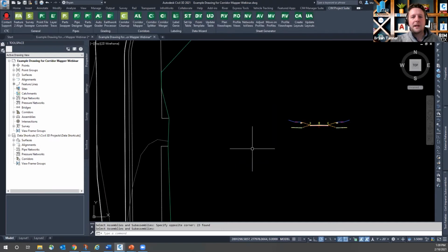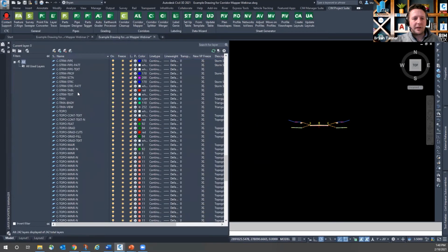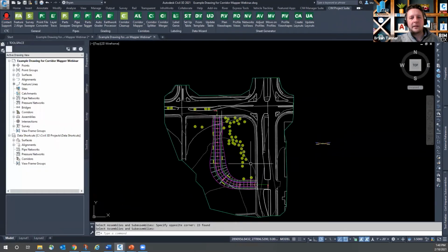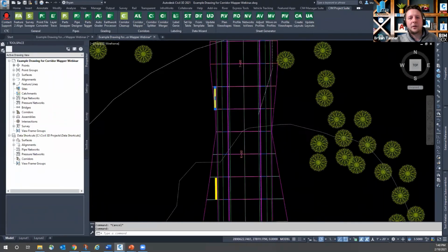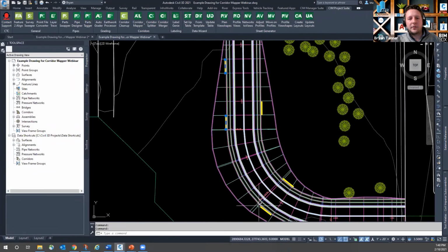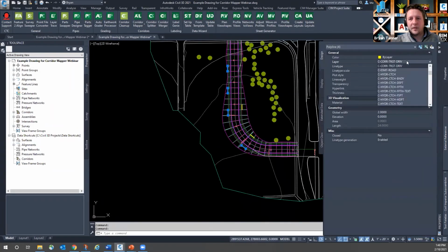So we'll go ahead and click OK. And in Civil 3D, if I look at my layer property list and scroll a little bit, I'm going to see that I have all of those subassembly names now created as target layers that I can utilize in my software. So if I had a conditional target left for my drives, I would place all of these polylines, either create them from scratch or take the ones that I already have, and I would place them on that